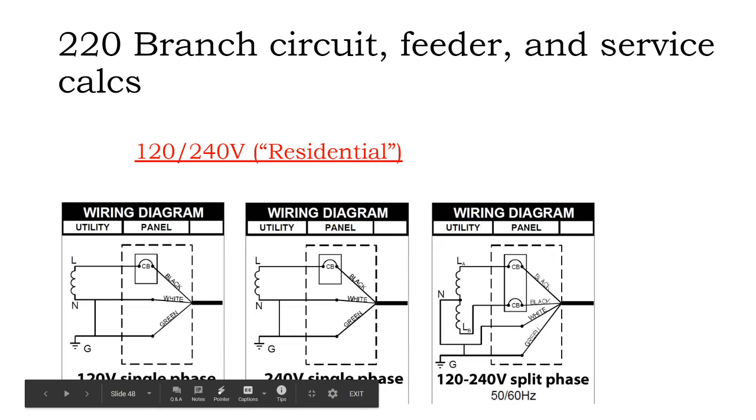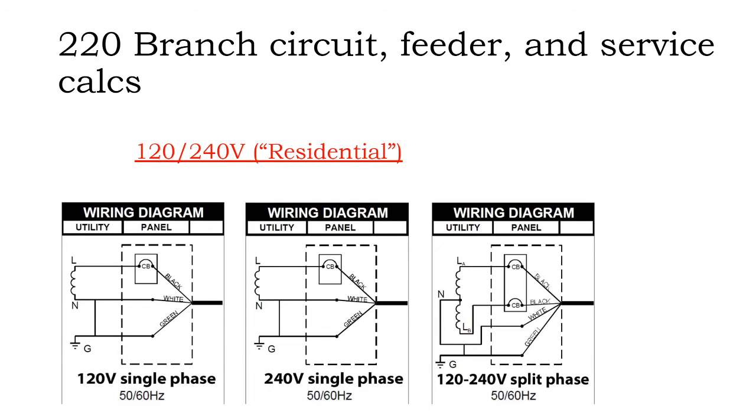But I guess what I'm trying to say is 120 is different than 120, 240 is different from 240. A 240 volt pure electric service will have a 240 volt leg, and then it's tied to ground. 120/240 has two separate 120 volt legs that, if connected together, because of the AC nature of alternating sine waves, can give you 240 volts.